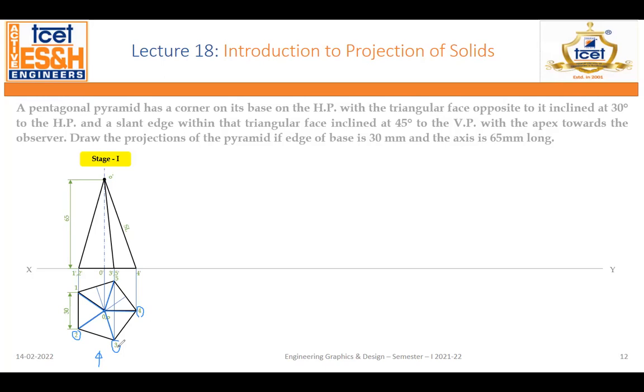So what do you have to make? Visible line. That is what visible line means. 1 dash is not visible as it is overlapping with 2 itself. So 1 and 2 are overlapping. Okay? So a hidden line and a visible line are overlapping, so you have to make the visible line. So with that, this stage 1 is getting completed. Let's see what is next.